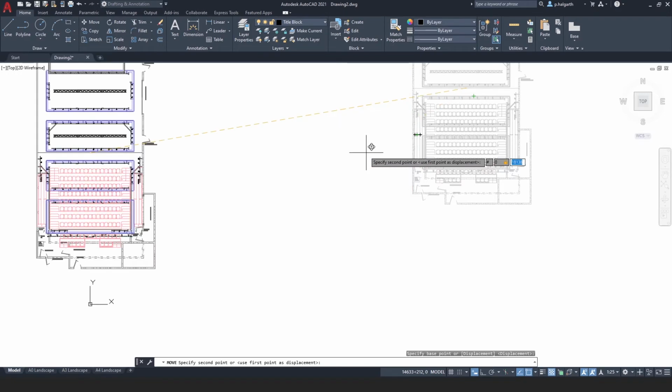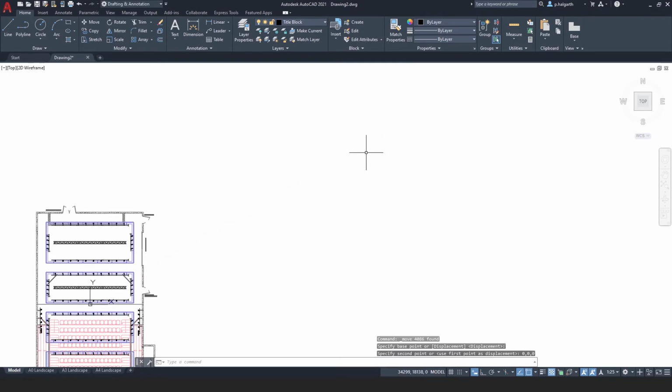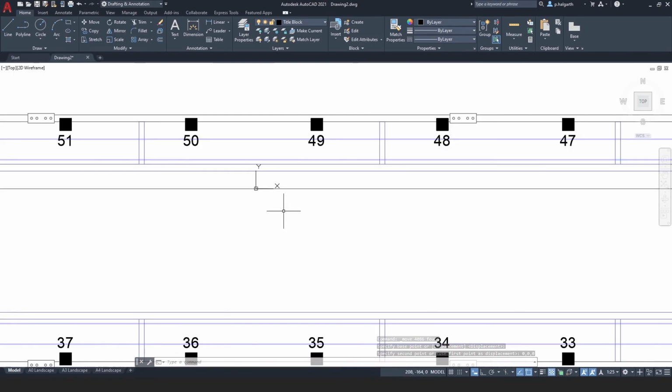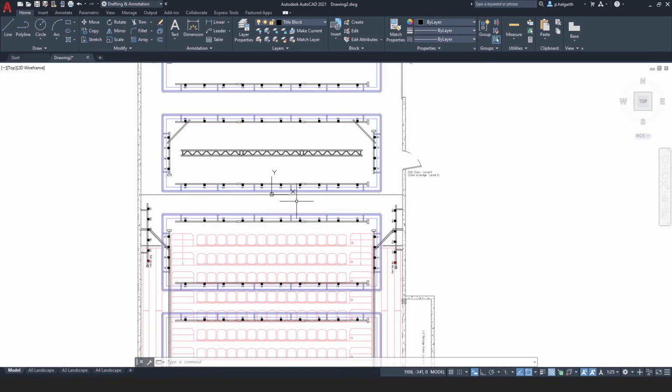Okay, and you can see already it's showing me where that's going to move to. Press 0 again for my Y, press comma, and now it's gone into position. And then the Z, of course I want that to be 0 because this is just a 2D drawing. Press enter, and you can now see that it's moved over to being exactly on the X and Y 0,0 of my setting line.